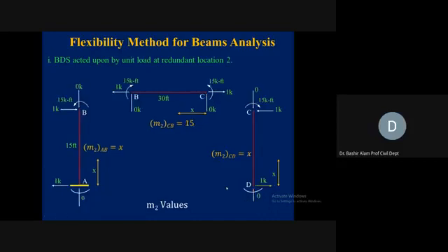Next now, corresponding to this, AR2 was a rightward directed 1 kip. So rightward directed 1 kip, we are applying at D now. Because of this, we are analyzing the whole members and the whole joints. How will we analyze CD? This was 1 kip rightward directed, so at C it is 1 kip leftward directed. Horizontally, the members are in equilibrium now. Vertical is 0 here, so 0 we have here also. Now this 1 kip and 1 kip is causing a couple. So 1 times 15 is causing a counterclockwise moment, so by a clockwise moment we need to balance it. So 15 kip-feet for this moment I'm putting at C now.